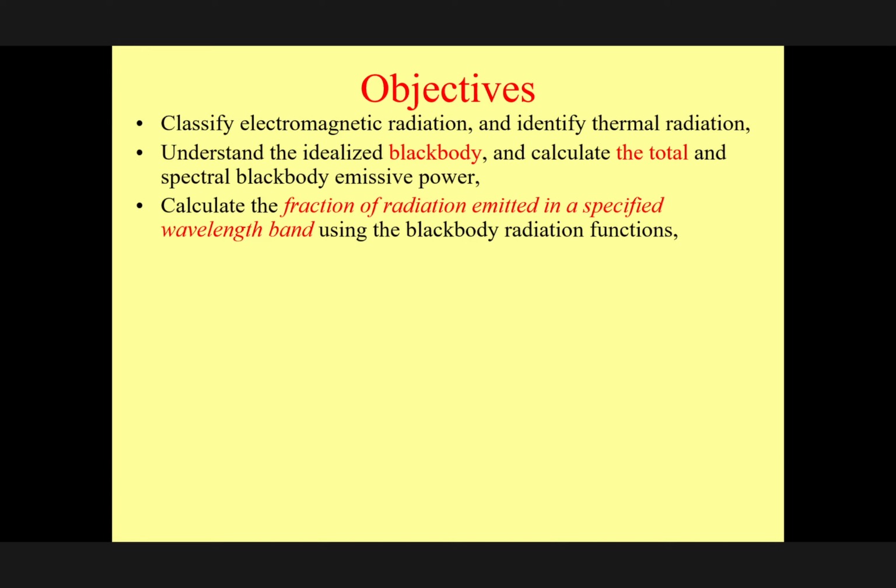For example, if I want to design a window, only a fraction of radiation comes in. Therefore, I can select my material that only accepts that wavelength. And this is very important when we are designing a solar collector, because we would like to calculate the maximum radiation. And you will see from that graph which part is contributing more.